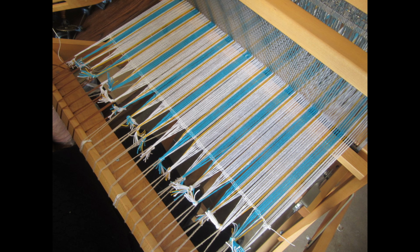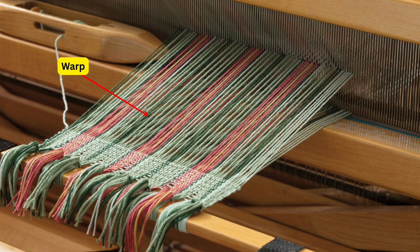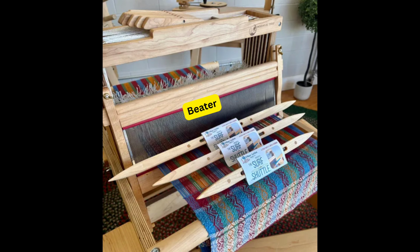You have all these individual threads, and you wish to join them together to make cloth. To do this, you need to lock the threads together going this way with another going this way. The loom holds a set of threads called a warp under tension in frames called a heddle that allows each set to be raised and lowered independent of the other. As each heddle is raised, a horizontal thread called the weft is pushed between the upper and lower sets of threads with a device called a shuttle. After each pass, the fabric rows are compacted with this device called a beater.